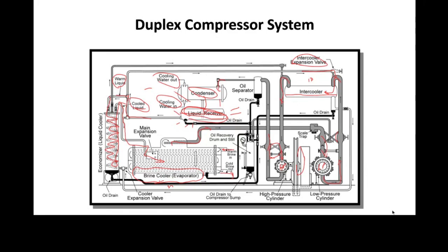Well, we put some refrigerant into it. Where did the refrigerant come from? The overfed intermediate pressure liquid from the intercooler. It's going to go la la la la la, as Dave Quintilio would say, through this pipe, and we've got an expansion valve here. And so the liquid is going to go in here and it's going to boil away on the outside of these refrigerant lines that are inside. And then we're going to suck here into the HP cylinder suction line.